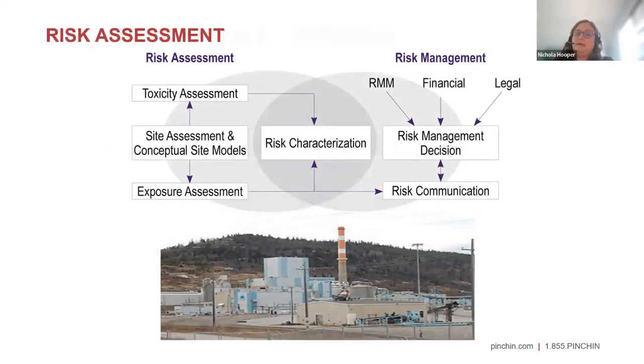So, risk assessment. At the beginning, I said the standards were developed using a risk-based approach. The risk-based approach that was used to develop these standards is called the generic standard. With the generic standard, they didn't take into account different factors like the depth of the impacts or whether the contamination is under a parking lot or a building. So we can use risk assessment to develop site-specific criteria, which might allow the impacts to stay in place, and you may not need to do any intrusive remediation. Overall, your remedial strategy can involve all three of the different approaches I just explained: ex situ, in situ, and a risk assessment approach.